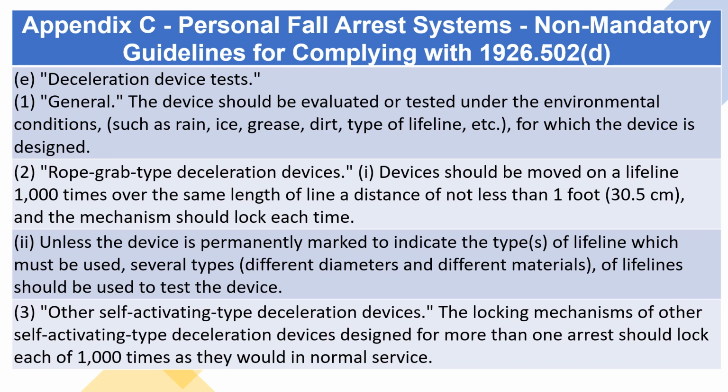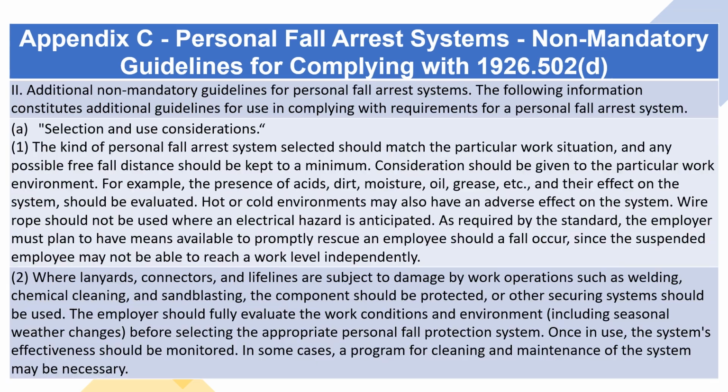3. Other self-activating type deceleration devices. The locking mechanisms of other self-activating type deceleration devices designed for more than one arrest should lock each of 1,000 times as they would in normal service. 2. Additional non-mandatory guidelines for personal fall arrest systems. The following information constitutes additional guidelines for use in complying with requirements for a personal fall arrest system.